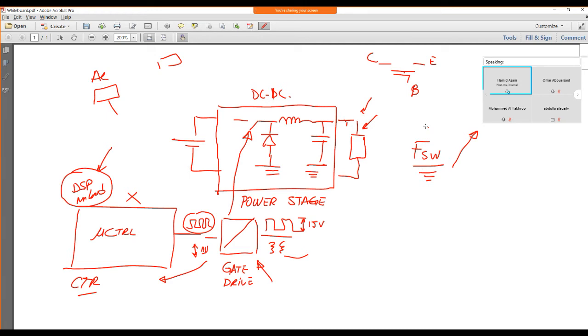By increasing the switching frequency, you're minimizing the size of the inductor, and this is needed. This is required in all designs because we need to design a small device. Small components will make a small device. So to have a small inductor, we increase the frequency. You keep increasing it to make the inductor micro size. But, and big but for that, there's a compromise.